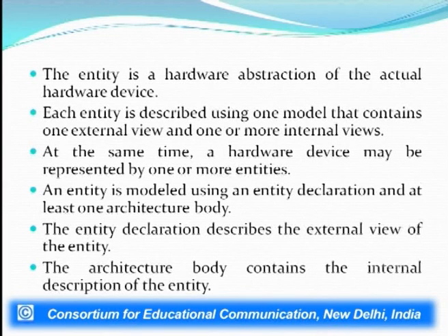Now coming to the entity, an entity is basically a hardware abstraction of the hardware device. It is described using one model that contains one external view and one or more internal views. At the same time, a hardware device may be represented by one or more entities. An entity is modeled using an entity declaration and at least one architecture body. It may have more than one architecture body, but at least one body will be associated with it. So the entity declaration basically describes the external view of the entity which is being described using the HDL. Now the architecture body contains the internal description of the entity.